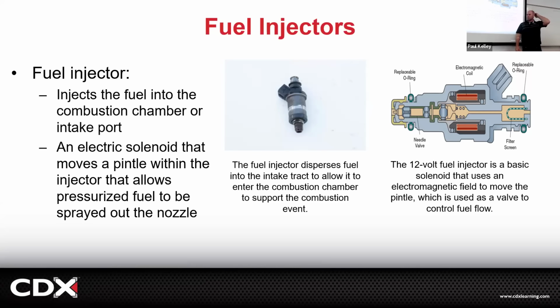So when we talk about misfires, I say fuel is the hardest one to get, right? You can check compression easy. You can check spark really easy. And then you're like, well, I think it's fuel. And it'd be like, well, how do I know if it's getting fuel or not? You can listen to the injector. If the injector is not ticking, it means electrically there's something wrong. But if the injector is ticking, that just means this pintle, this needle and seat is moving, but that doesn't verify that there's no rust in the screen. That doesn't verify it's getting a clean spray pattern, right? So it's kind of hard to test them.